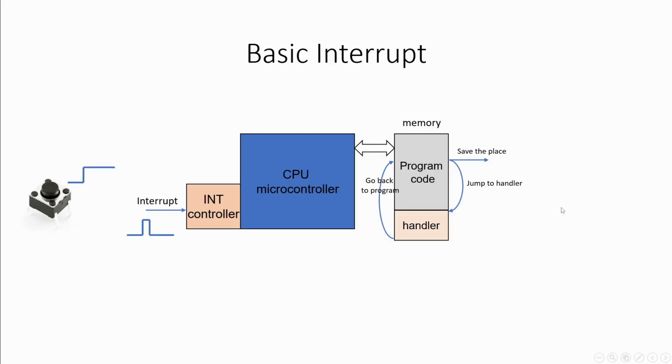One more thing is that I'm generating the interrupt by a push button. The push button is a very slow interface and has to be pushed by hand, so I might tremble and it might take a while, so I'm adding a debouncer.